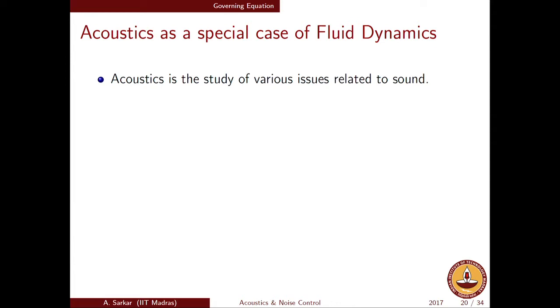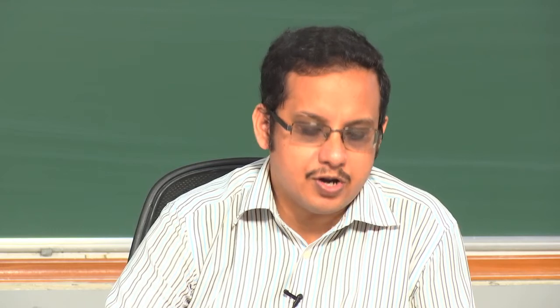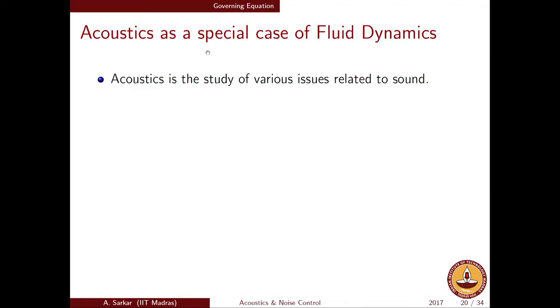So, therefore, the perspective that we will look at is that the sound transmission within the fluid medium, in particular air, is just a special case of fluid dynamics. It is a fluid dynamic phenomenon because of which the sound is travelling from one point to another, at least within the air. We are not talking about structure borne sound, at least for now, but we are talking about the transmission of sound from the source to the receiver. This is basically the transmission of pressure fluctuations accompanied by density fluctuations from the source point in the fluid to the receiver point. Accordingly, we will treat acoustics, or more specifically sound transmission, to be a special case of the fluid dynamic equations, and that is how we will derive the governing equations of acoustics in the present class.